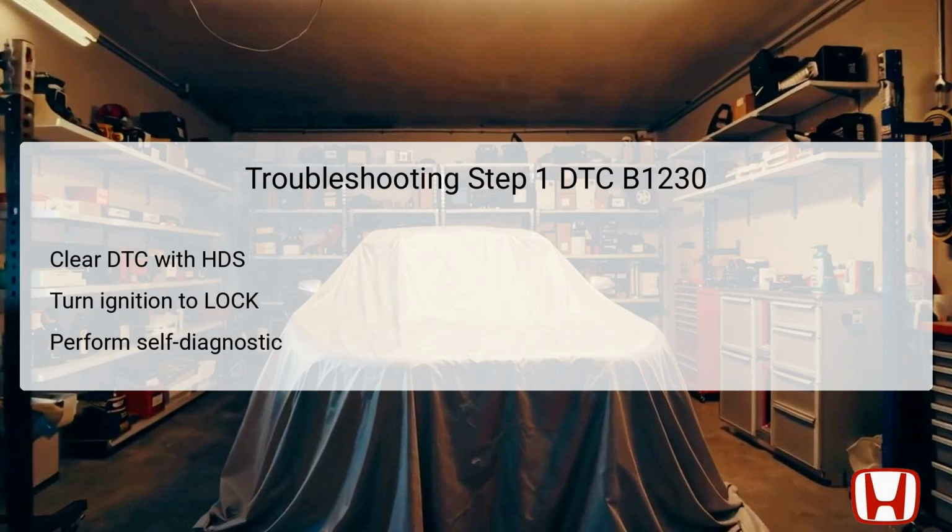Following this, perform a self-diagnostic with the HDS or the climate control unit to check for any stored DTCs. If DTC B1230 reappears, it indicates a persistent issue in the sunlight sensor circuit. If it does not, there may be an intermittent failure that could relate to loose wiring or poor connections, which should also be checked. The second step in the troubleshooting process focuses on checking the sunlight sensor itself.